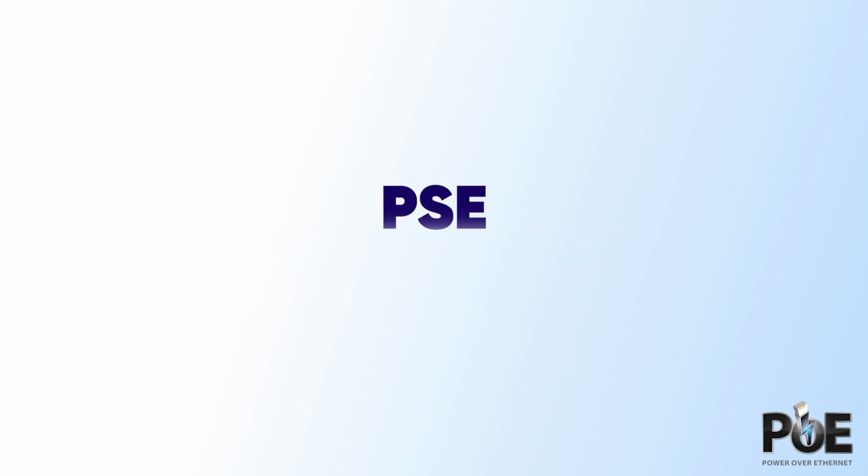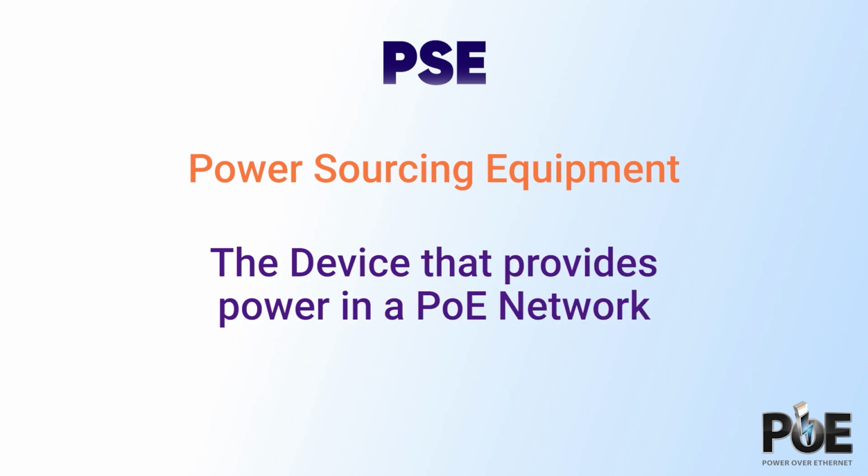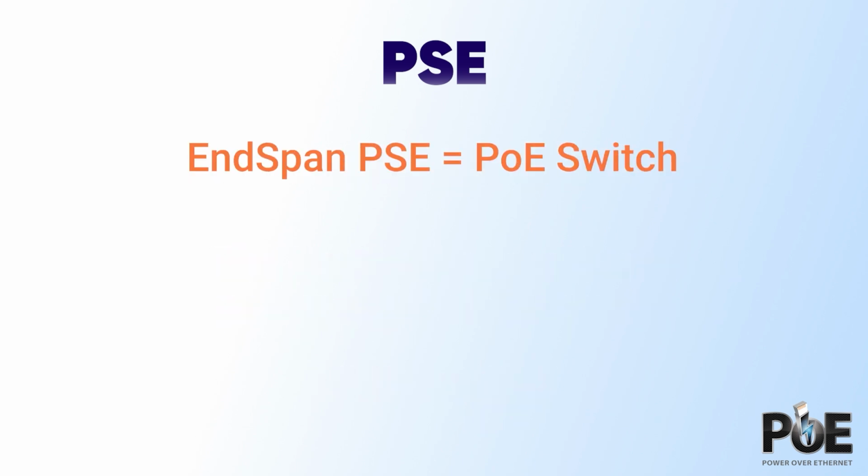Terms like PSE and PD are used when discussing PoE technology. PSE stands for Power Sourcing Equipment. This is the device that provides the power in a PoE network. It may be an end-span PSE located at the end of an Ethernet link segment, or it may be a mid-span PSE located in the middle of an Ethernet link segment. A PoE switch is considered an end-span PSE.